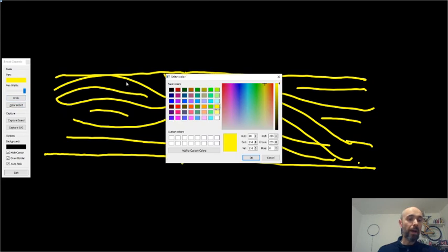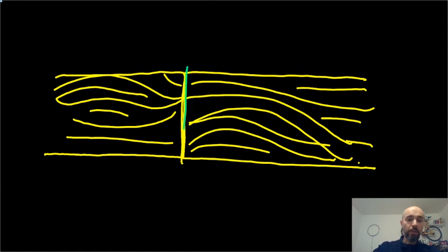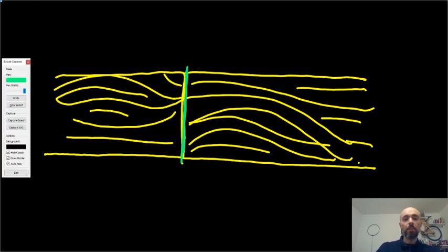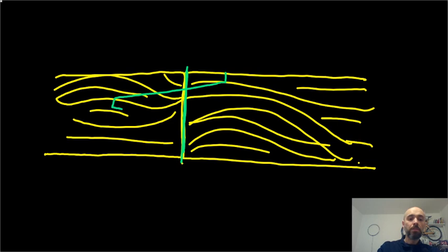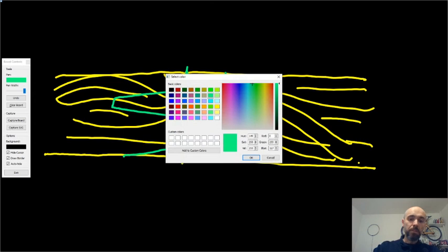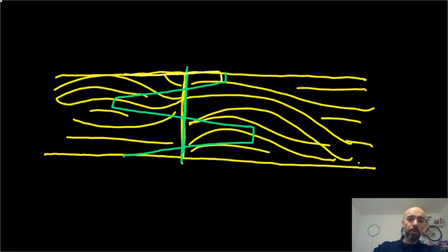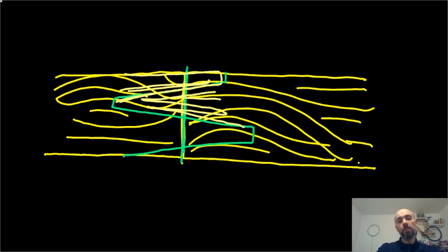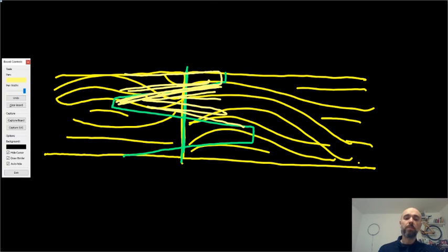The only way you have to make it more resistant is, instead of gluing this line here, you cut both borders with a zigzag line. Now what happened is that at this point the fibers get more parallel somehow. So you have fibers that gets up to this point, and in the other direction you have longer fibers here. So the connection here is going to be much more resistant.